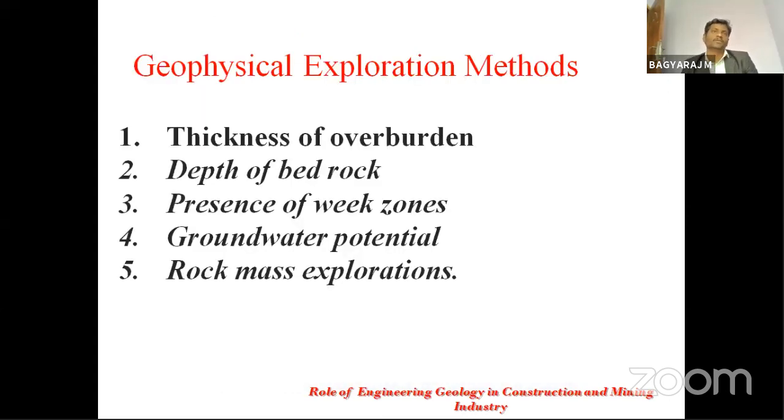Then go for geophysical exploration. Geophysical methods find out the thickness of overburden, depth of bedrock, the presence of weak zones, groundwater potential, and rock mass conditions.